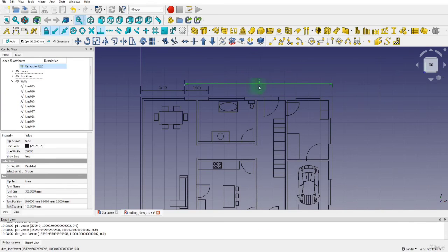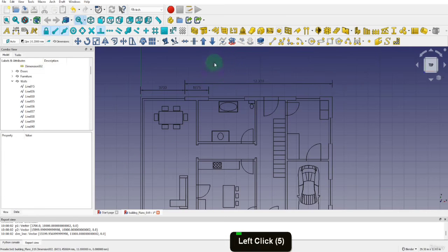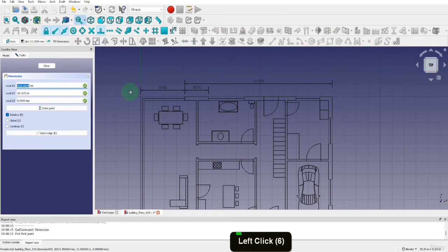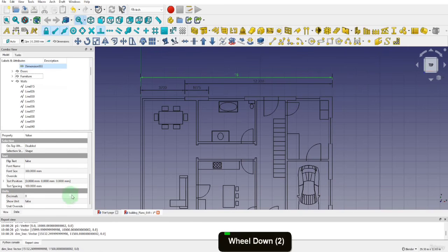This time the decimal value can be increased because this is displaying meters. So increase this to 3 in the View tab. Let's select the dimension tool again. This time we can get the full length of the building. Snap to the first point, then the second. Press Y, this time input 1500 and move this out beyond the last dimension. This will also need the decimal value increased to 3.